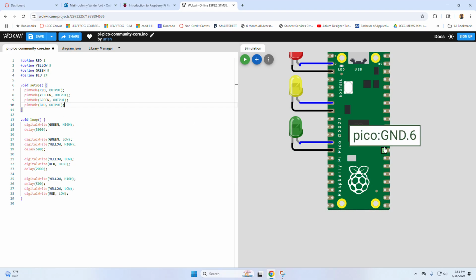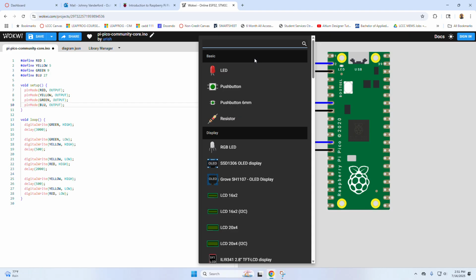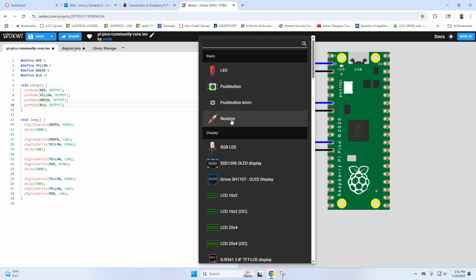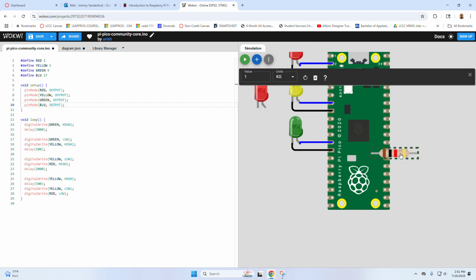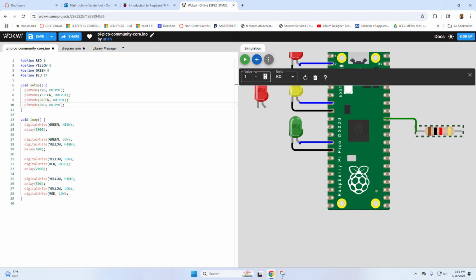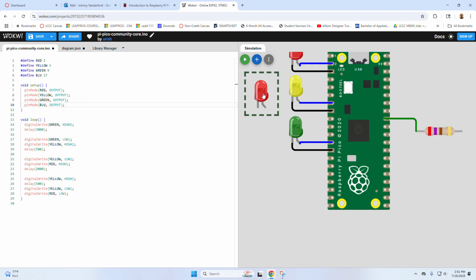So now I also should probably add an LED to this here. So I'm going to add 2 things. I'm going to first add an LED, but I'm also going to add a little resistor for this as well. This resistor, I'm going to tie this to general purpose. Most LEDs need some form of a resistor in order to block the flow of current going through them. We'll make this one like a 270 ohm resistor. Notice it changes the stripes accordingly for those, so that's kind of nice to do.